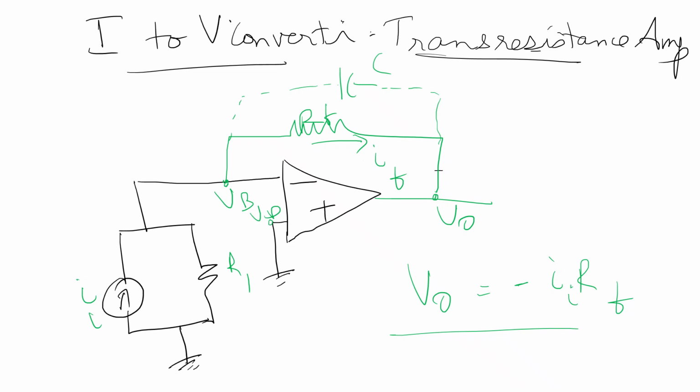This may be pointed out: the lowest current that this circuit can measure will depend upon the bias current of the op amp. This means that the IC741 used here can be used to detect lower currents. The resistor RF is sometimes shunted with a capacitor CF to reduce the high frequency noise and the possibility of oscillations. Here the input current source is connected to the inverting terminal.